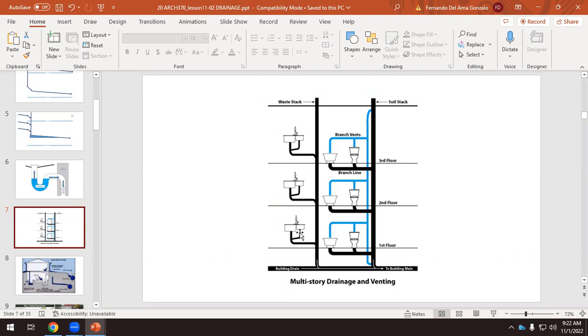But for this one, we have to recover. So some of the points that we get from the LEED certification come from the reuse of that water. This is not something that you can drink, but probably you can use this for watering the plants, or after a treatment, not a very special treatment, we can use the water that comes from that gray water, and then we can recirculate this gray water to go to the toilets. So we don't use the water that comes from the city to flush the toilet. We are not going to drink water from the toilet, at least not in this country.